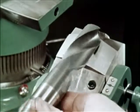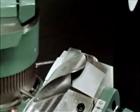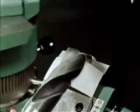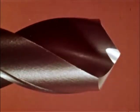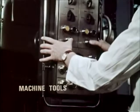The core or web of a drill increases in thickness towards the shank to give the drill rigidity. Therefore, as the drill is shortened by repetitive sharpening, it becomes necessary to thin the web at the point. This operation is better performed mechanically, as it is essential that it is correctly formed and equally balanced about the drill axis.